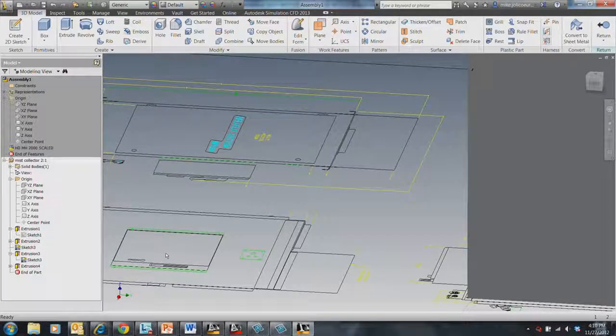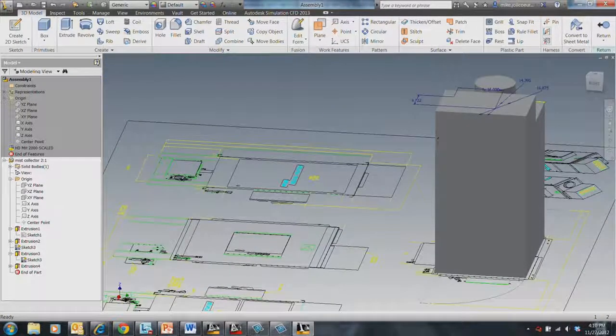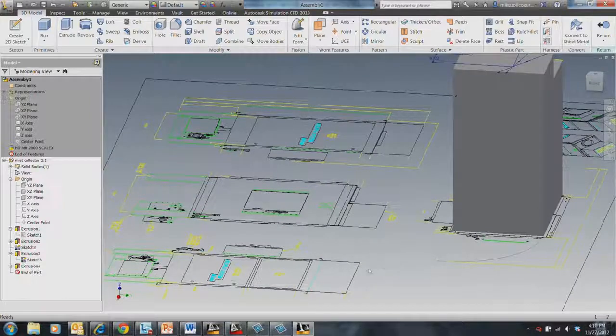Why is that? Because we have to have 36 inches between these. And a friend of mine used to call that the bacon distance. And what do you mean by that? Because if you're any closer to that and you touch the inside of that box, you're going to fry, just like a piece of bacon. So that's what he called the bacon distance. So you got to make sure you got that clearance. So it's important that we're able to show those types of things on our models.